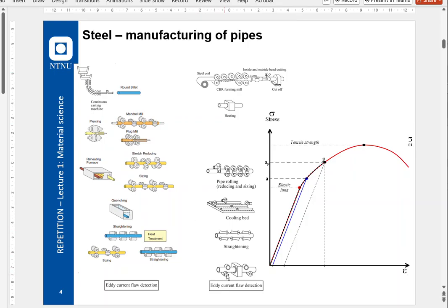To the left in black and white, we have the welded type of pipe, which would typically be from size 20 inch and above. You will of course get special sizes like 13 5/8 and so on, also in welded qualities, meaning that you'll probably get whatever you like to order with the casing tubing manufacturers.